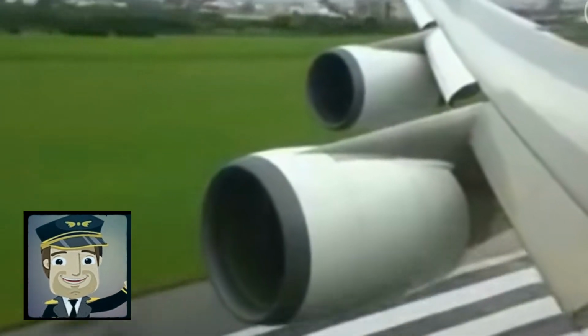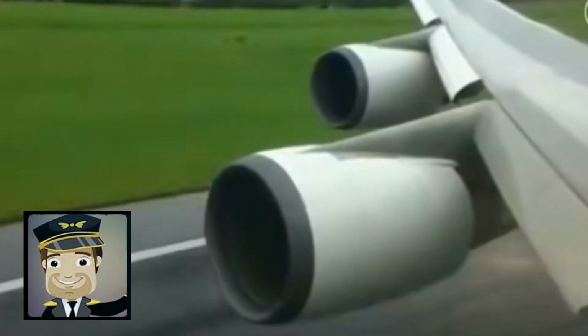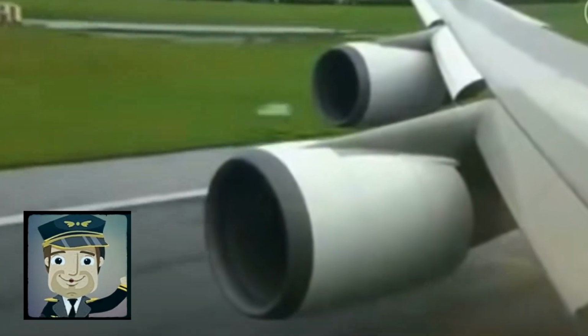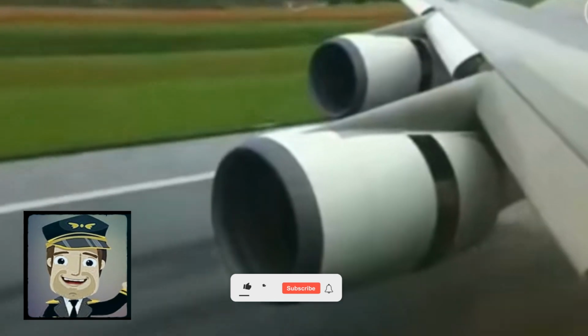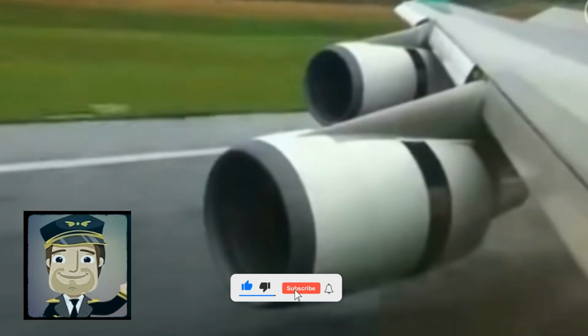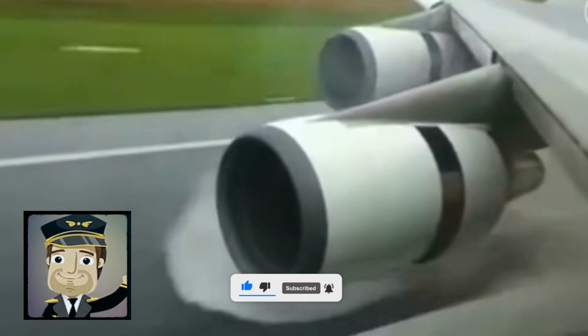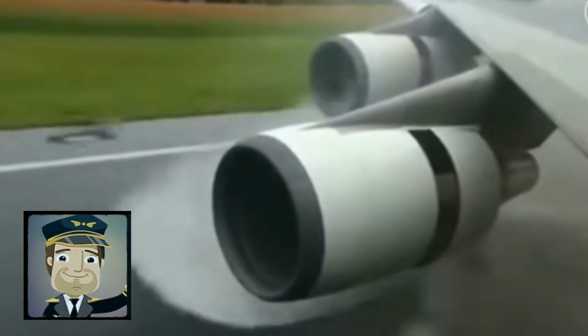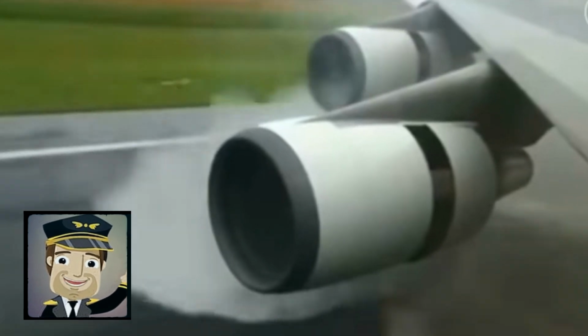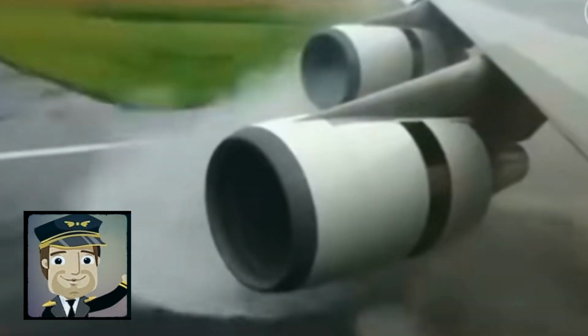Thrust reversers are not used in flight. Their use is restricted to ground operations immediately after wheel touchdown, and their activation depends on the landing gear being fully deployed. The system is designed to work in conjunction with aerodynamic brakes and wheel brakes, giving the pilot greater control over the aircraft and helping to reduce the runway length required for a complete stop.